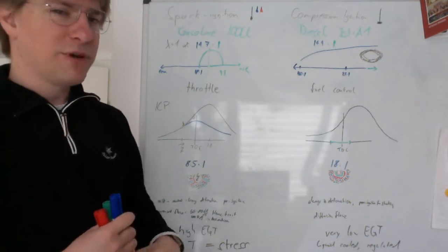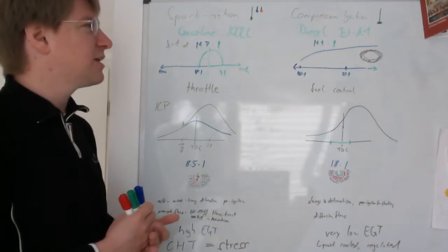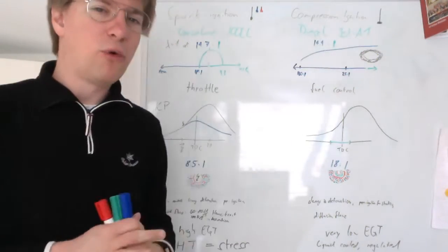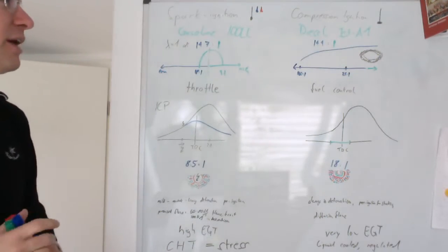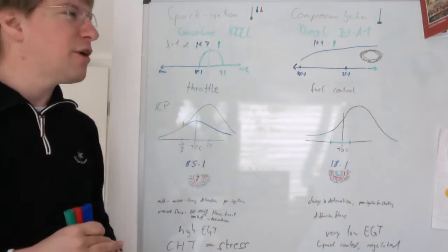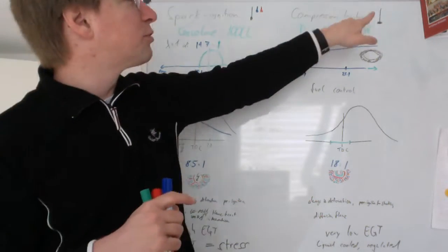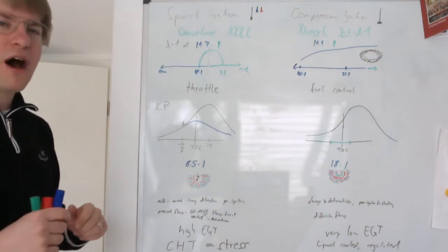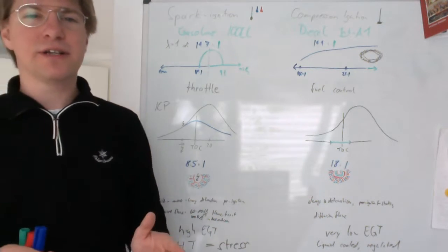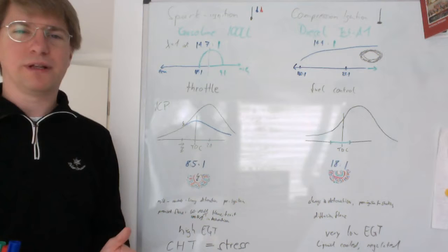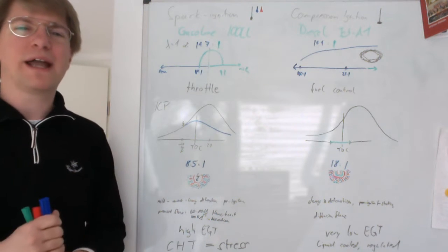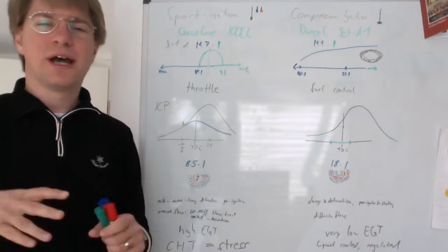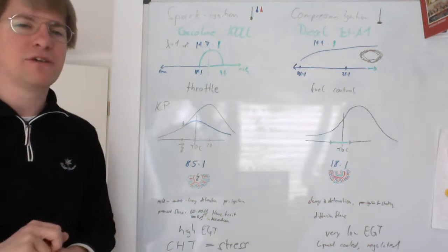On the other hand, with the diesel engine, with the compression ignition engine, we only have one lever, the power lever. Let me make it clear though that having no propeller control, no blue knob, is not inherent to the diesel principle. There's no reason why the diesel-powered Diamonds could not have a manual propeller control.